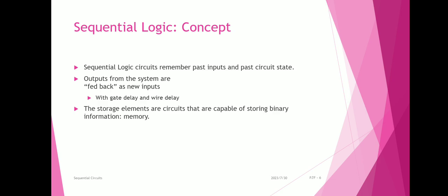Nearly all sequential logic today is clocked or synchronous logic. In synchronous circuits, an electronic oscillator called a clock generates a sequence of repetitive pulses, which we call the clock signal. It is distributed to all the memory elements in the circuit, and the basic memory element in synchronous logic is the flip-flop.